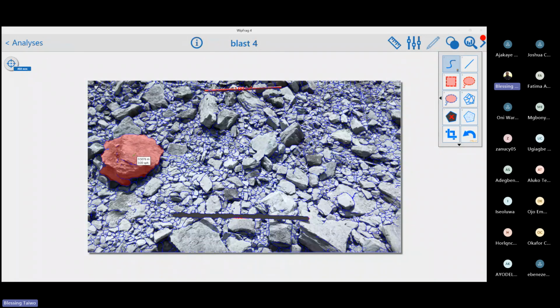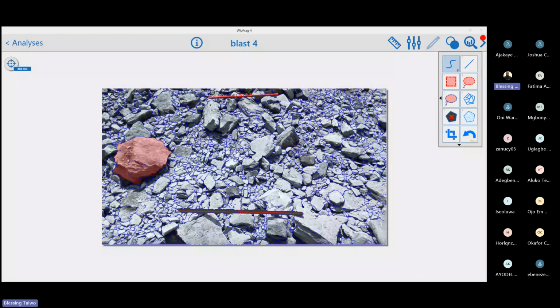The size of this material is 0.5076 meter, which is 507.6 millimeter. And definitely that material will not go through our crusher of gap 500 millimeter. And you can see how to use that to assess your blasting. And what can you use this to do? When you want to give direction to your loading, you tell your loader where that material is located so that you don't keep doing the sorting and finding where that material is, and you don't do guesswork.